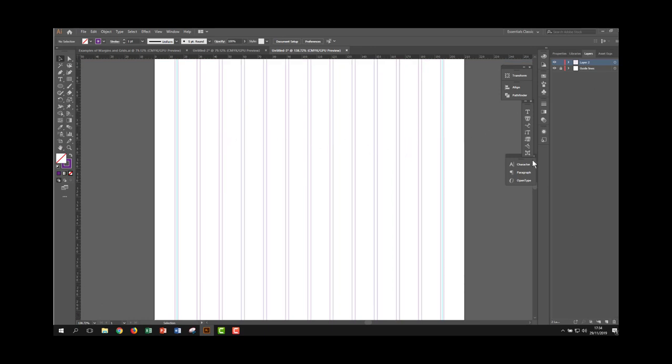So again, I'm going to go to the Layers panel, go down to the bottom, to the New Page icon, which indicates creating a new layer. I'm going to work out where I'm keeping my grid lines by using the Hide and Show next to the layer, so I can see at the moment my grid lines are in layer 2. I'm going to call this grid, press return.